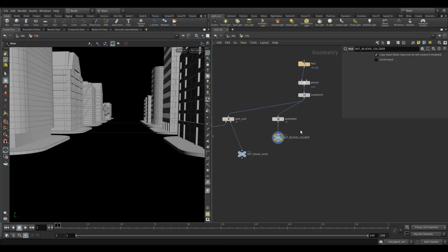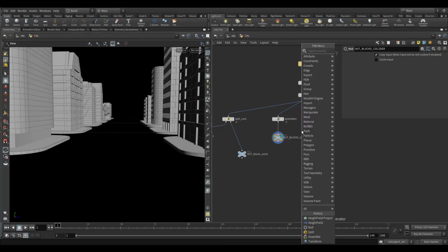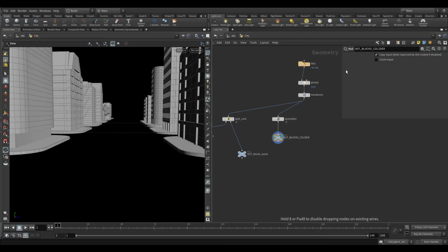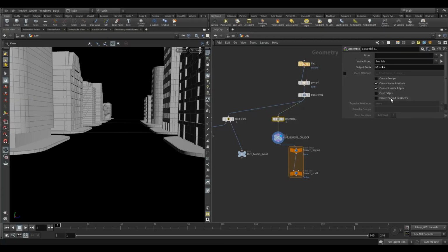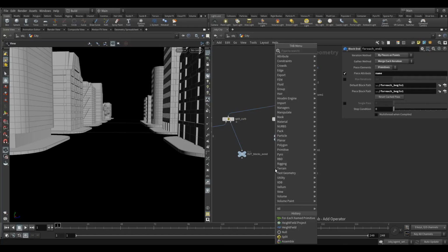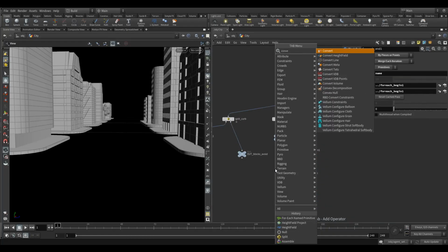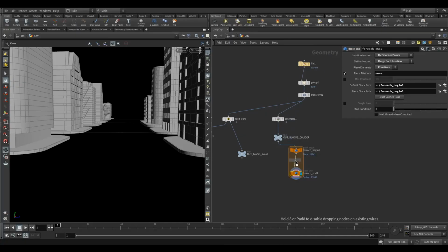Just to check these, we can do the same thing we did in the last project. We use a for each loop, connect that with just the first one up there, just unpack it temporarily, visualize that, so that will go over every piece, and then drop a convex hull.